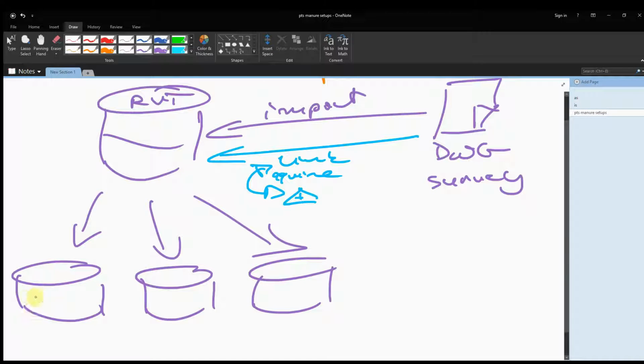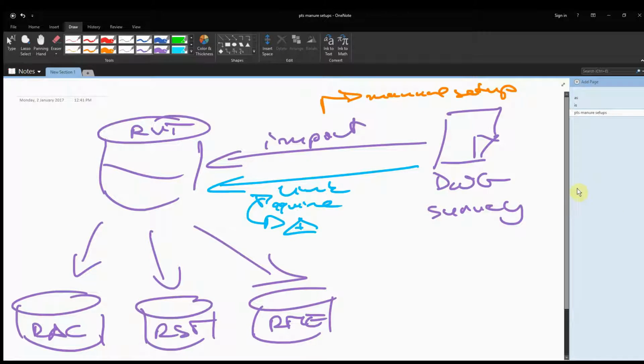So in the industry you would find RAC, Revit Architecture, Revit Structure, or Revit MEP. Probably what is better, linking or importing, decide for yourself, whatever you need, whatever you love to maintain. If you want a good tip: large projects, import; small projects, link it. What is large, what is small, make up your mind.